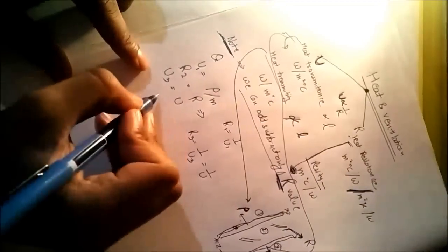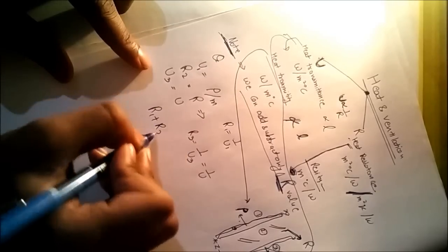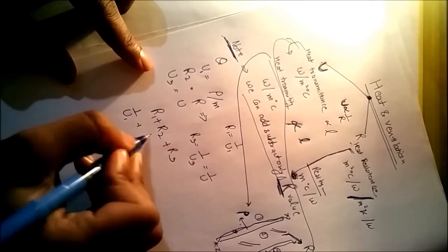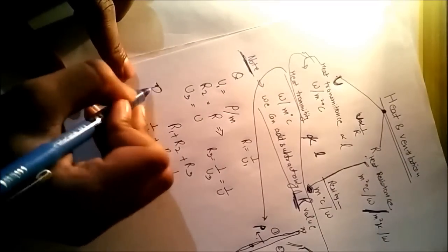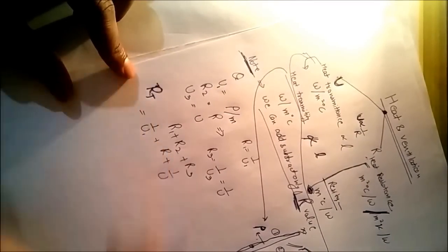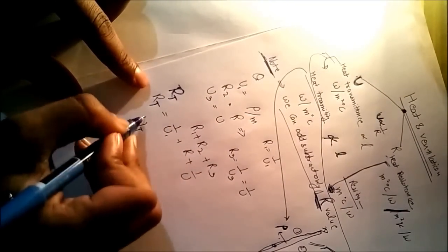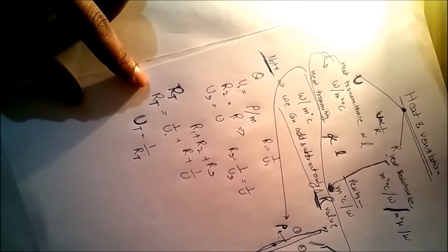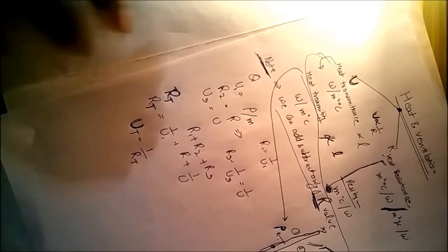It's very simple. Now we can add all these values, R1 plus R2 plus R3, that is 1 upon U1 plus R plus 1 upon U, the total R. Now if they ask for the total U value, after finding the RT, the total U value will be 1 upon RT. This will be the total value.